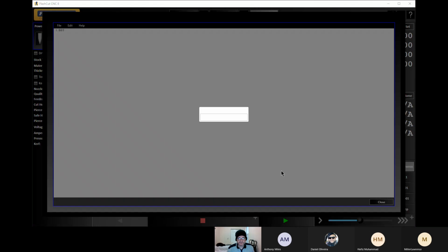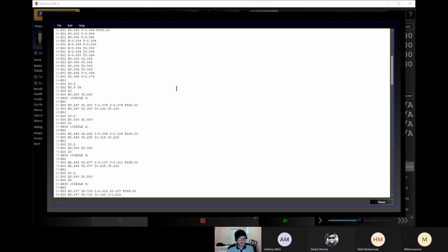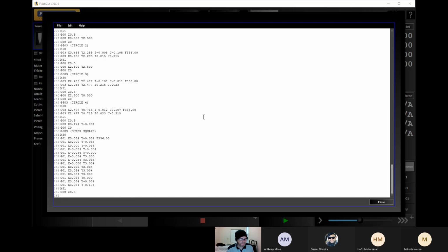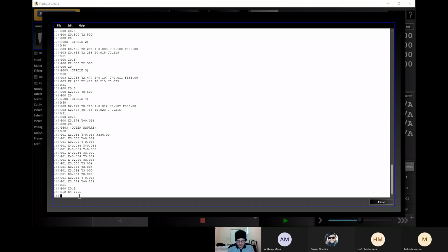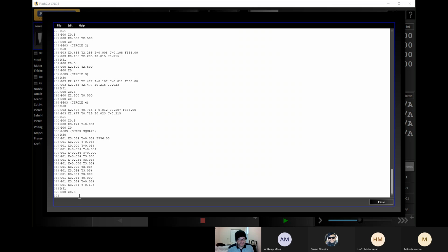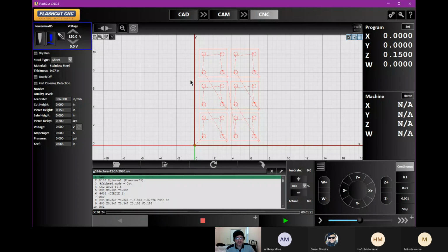Okay, so we go into our pencil, scroll down. This will be the last one we put in. All right, put on our G52. We do X4, Y 7.5. Put in our G00 to bring our torch back down. Hit Control V. Paste everything. Save it. Close it to check it out. Okay, so